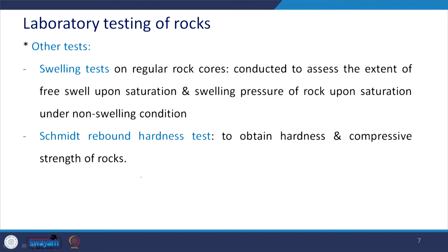Then in this series, the next test is the swelling test on regular rock cores. This is conducted to assess the extent of free swell upon saturation and the swelling pressure of the rock upon saturation if it is under the non-swelling condition.